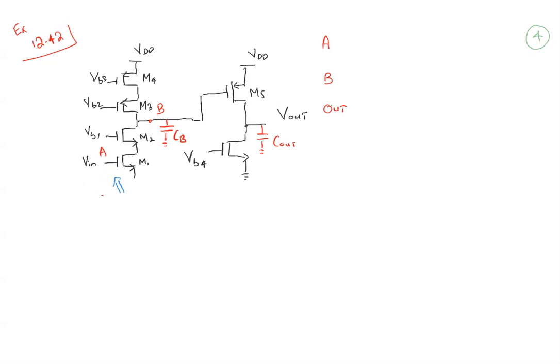If we want to talk about what is my, I guess there's some small mistake here. The first one given is the capacitance at this node, because that will not be dominant, so that we can ignore. So this is the node A between the drain and the source of M1 and M2. So node A is this. So what will be the pole because of this capacitance CA?